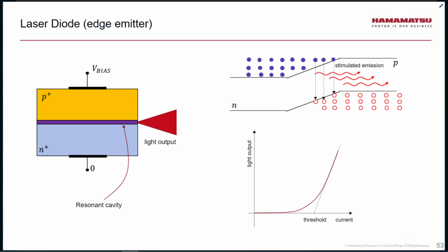So the inversion here is achieved by biasing, by injecting current, so that you have overpopulation of electrons in the conduction band, and likewise a large population of holes in the valence band. And so an electron goes down, recombines with a hole, producing a photon, but that photon will stimulate subsequent electrons to do the same. Of course, they replenish the electrons by continuing injection of current. And so the lasing action is taking place.